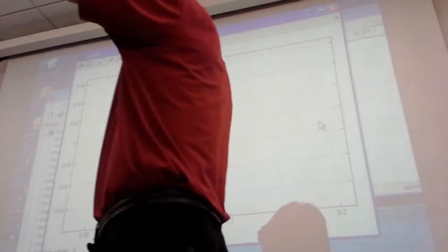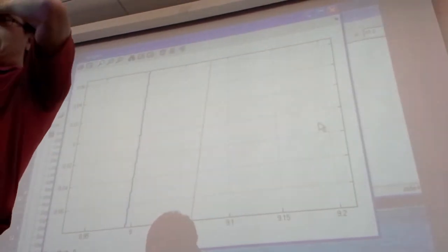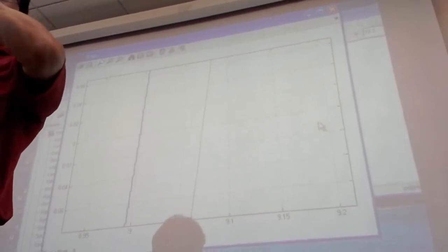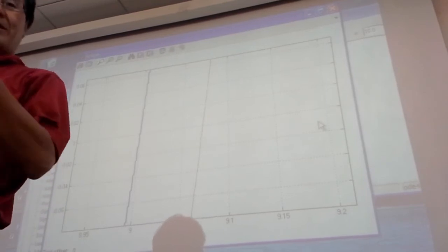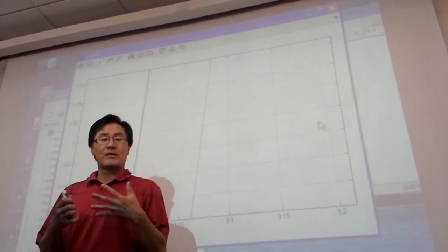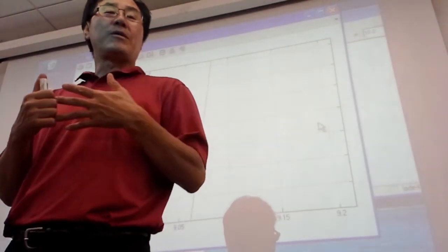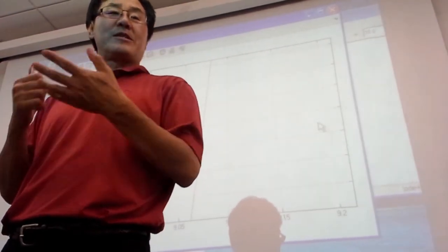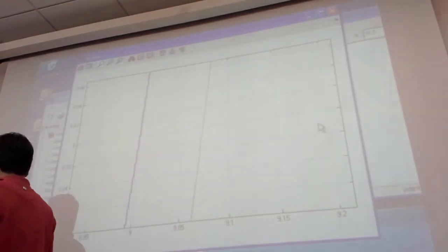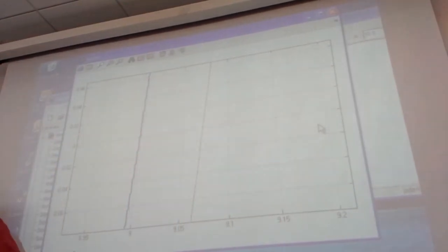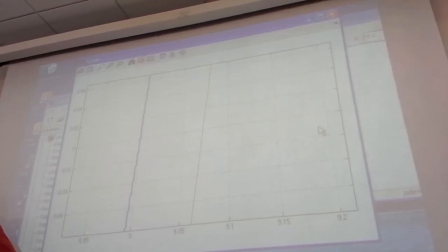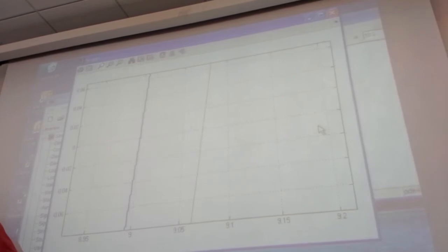I always give this problem in the test because that's very important. You have to understand how much phase delay you have. In lots of cases, if your system is unknown and I want to find out how fast the system is, you apply a sine wave signal, especially at the frequency you're concerned with.